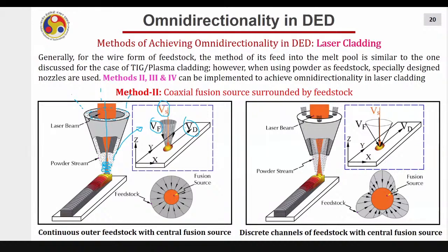We have discussed it yesterday, because when you tilt such nozzles, the direction of the powder becomes more at one end and another end. Also, FGMs are not really very easily possible here. So 3 nozzle systems also can be used. That is why when I was discussing yesterday, I always say minimum 3 nozzles are preferred in all the systems. Then you increase, like I already said, you use 30, 40, 50, that doesn't matter. But minimum 3 is required, because 3 can approximate a cone.